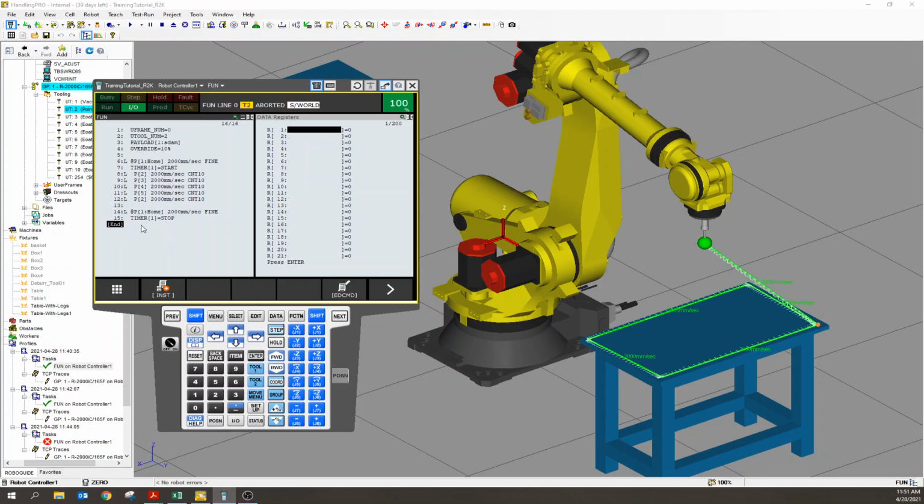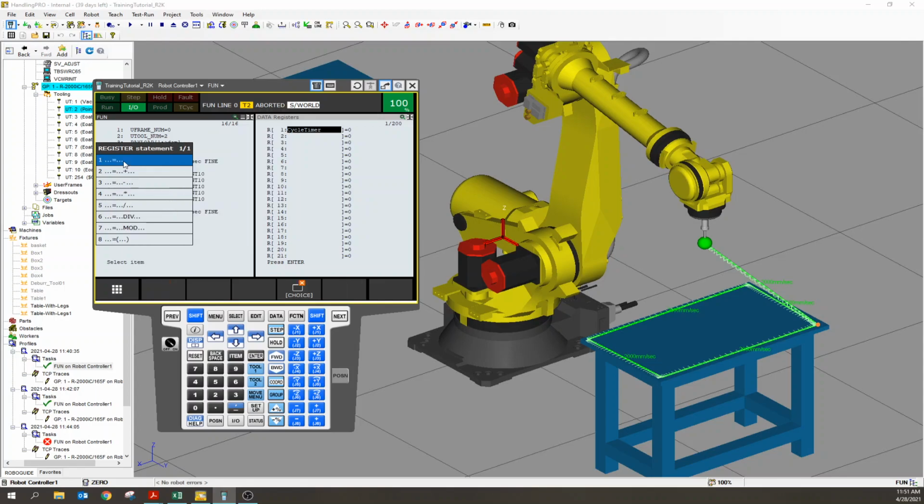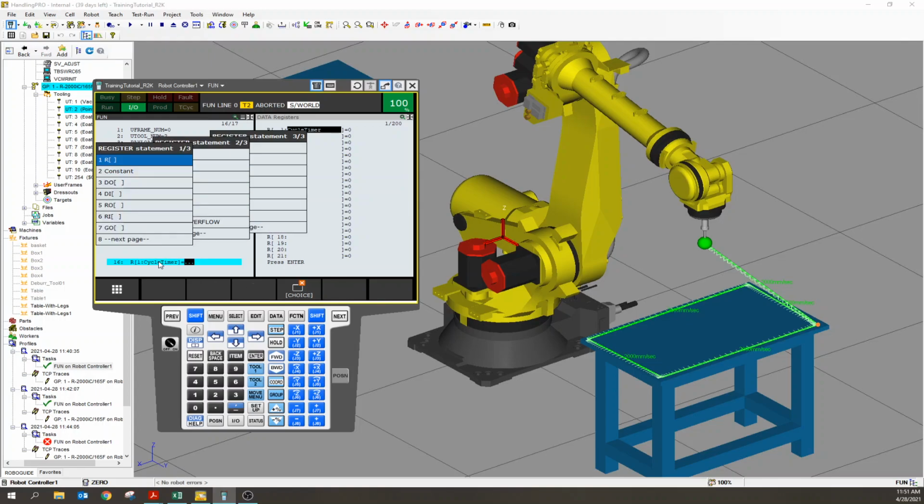In this example, I'm just simply going to push it into a register. That register maybe goes to your PLC or goes to an HMI, whatever it may be, a process logger. Let's go ahead and do something. I'm going to define register 1 as cycle timer. And I'm going to add another instruction, add register, and say register equals. I want to choose register number 1. You see register 1, cycle timer equals, what does it equal?